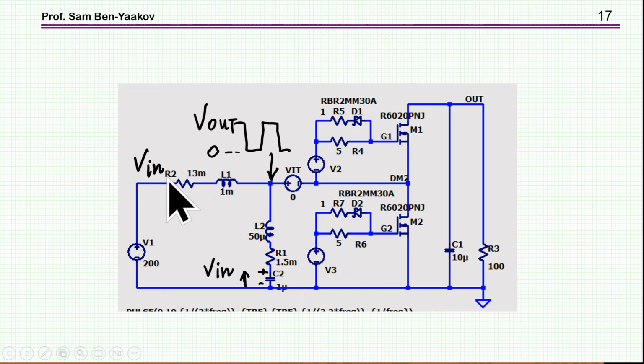So just to summarize what has been done here, we have a larger inductor so that this inductor is just carrying primarily the DC current, so it can be an inductor for a lower frequency using perhaps amorphous core and some other means that are less effective for the high frequency AC, but here we don't have a large component of AC.